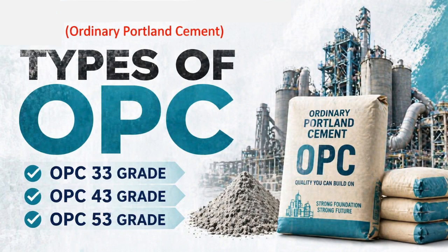The first grade is OPC 33 grade. This is the lowest strength grade of OPC cement and is generally used for basic or non-structural work, for plastering, masonry, and simple concrete work where high strength is not required. OPC 43 grade, this is the medium strength grade of OPC widely used in general construction such as residential buildings, RCC work, flooring, and plastering. It offers a good balance of strength and workability.